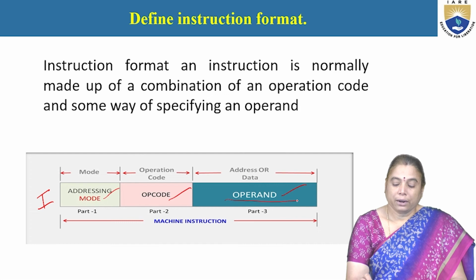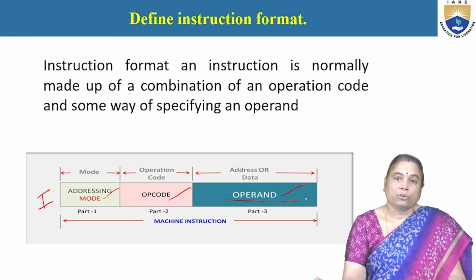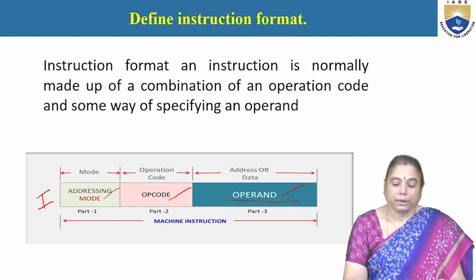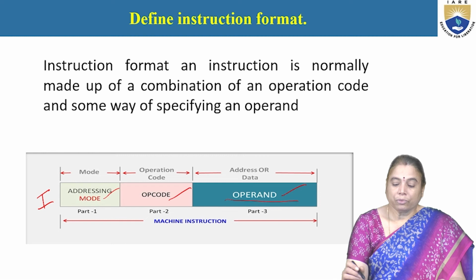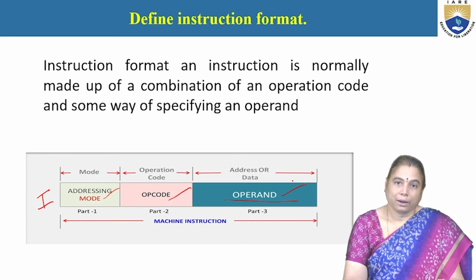The operand address specified here is the effective address of the operand. Another memory cycle is required to fetch the actual operand from the memory. So, two cycles are required to access the operand in case of indirect addressing mode. Generally the 0 to 11 bits are used to specify the address. The next 3 bits can be used to specify the opcode. The 15th bit is used to represent the I value.